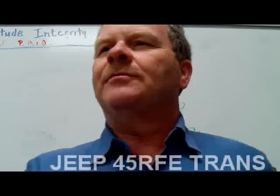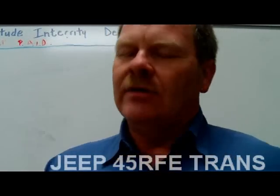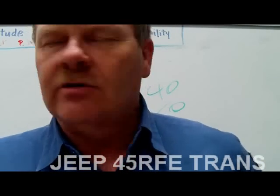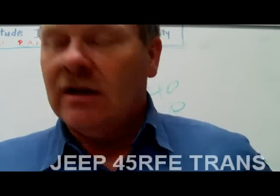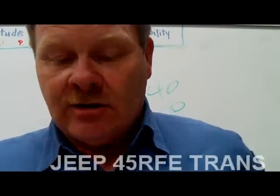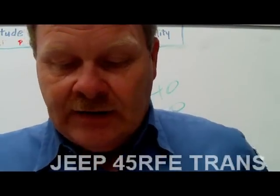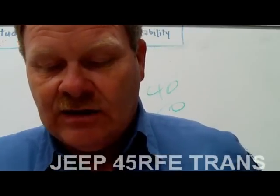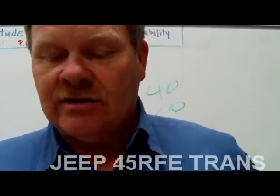Turbine shaft, we're going to measure the speed of that, and we're going to measure how fast the output shaft speed is going. We're going to compare those. When we know we're telling it to be in a certain gear, we know how fast those are supposed to be turning, don't we? We're also paying attention to how fast the engine's turning. But for the transmission's purposes, how fast the turbine speed is turning is all important. That provides the TCM with gear ratio information, and the crank position sensor supplies it with engine RPM data that's critical to schedule and shift point.